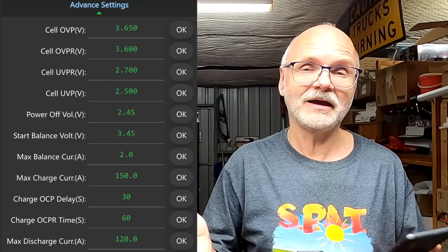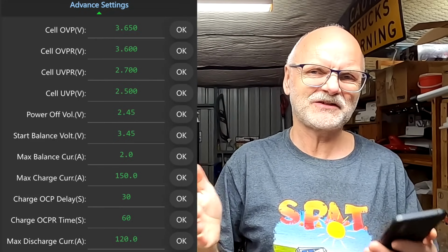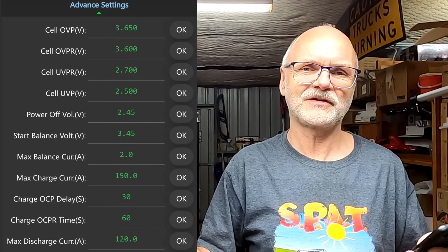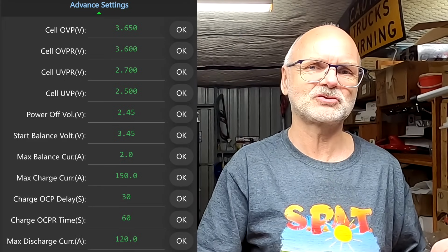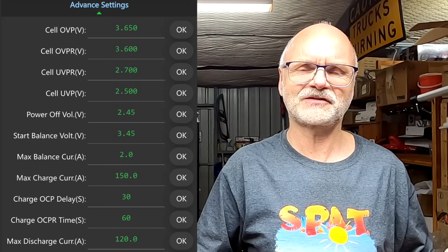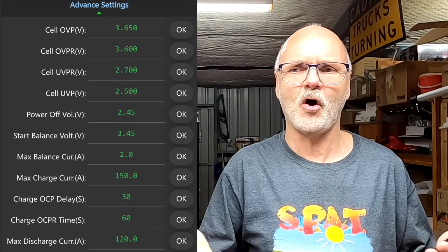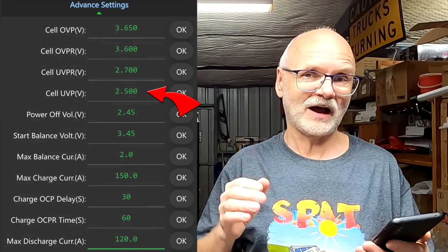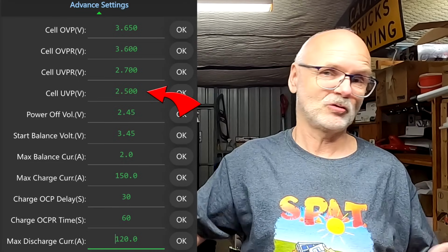I'm an extreme guy. As you may know, I do some testing here and there on the channel, and I like to fully charge the batteries to 3.65 and fully discharge to 2.5, just to measure something, to test something, to explore, and just to annoy other people because I'm going into the extreme. And here again, if we hit the 2.5 volts, the BMS will shut down your whole battery.